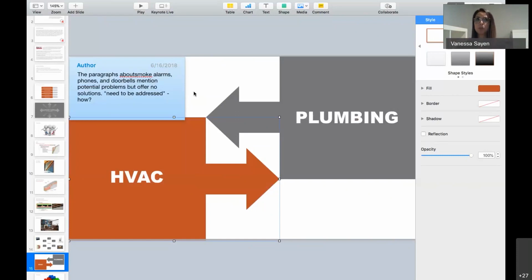Also, the grills in a room can whistle if the volume of air passing through the system is too great. So that's something to work out with your HVAC company, to make sure we have the proper amount of AC vents, and there's a formula for that. Sometimes increasing the number of vents, making them bigger, or using different methods can help greatly. But again, this is where the conversation starts, and we make sure everything is planned accordingly.